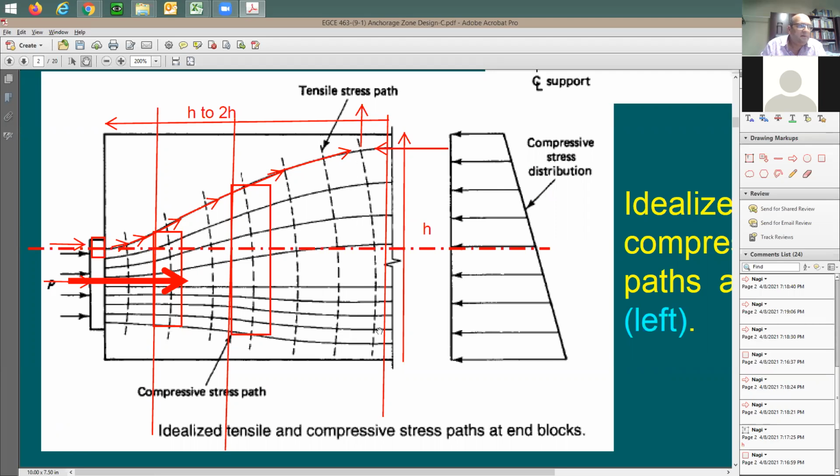So this dashed line represents tensile stresses in the y direction. It's going to be like this. And on the bottom it's going to be like this. Okay? So here's the problem. Once you put some compressive force here, it wants to open up this block. Now, how would you resist it? I mean, what is the easiest way of resisting this? You can say just add ties. So what I need to add is some ties in this direction here, right? This gives you a tie, and here's another tie, like rebars. These are stirrups or ties, and this tie is going to be taking this tension force.